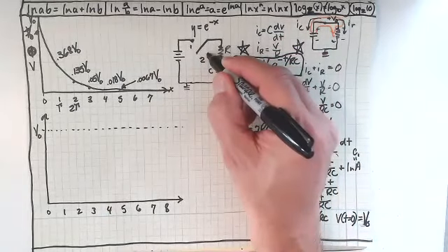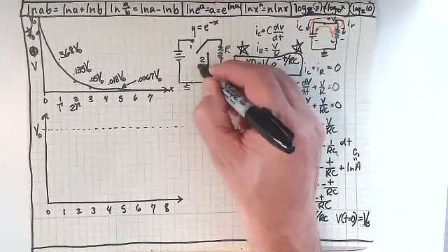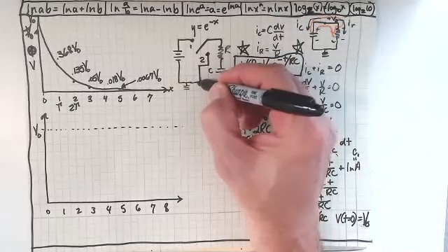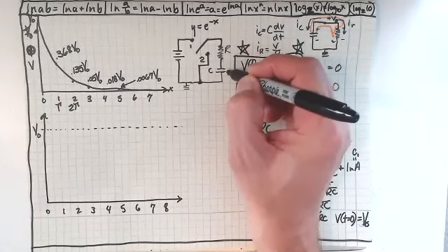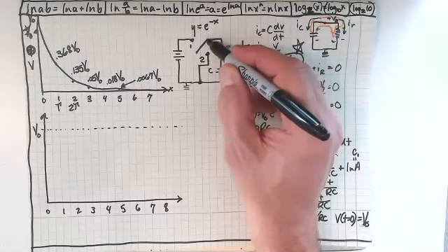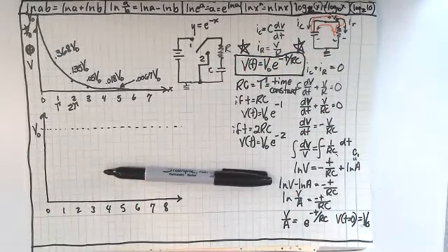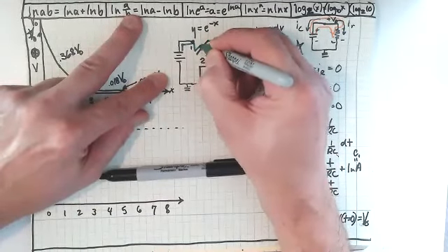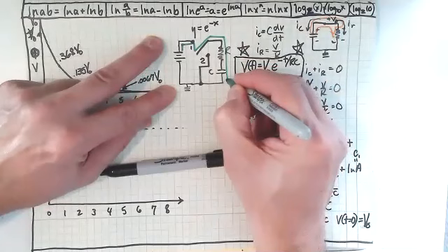Now, that second thing right there is connected to ground, right? So if this swings over here, then the charged capacitor is going to discharge through the resistor to ground, right? So we've really got two pathways there. We've got a pathway for the charging, because for the charging, we would just have this, right, through here, through there, and that would charge the capacitor, right?